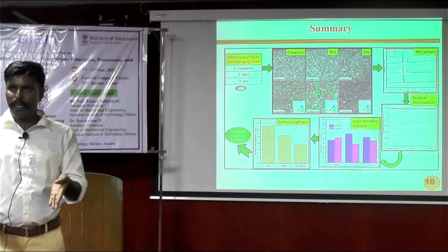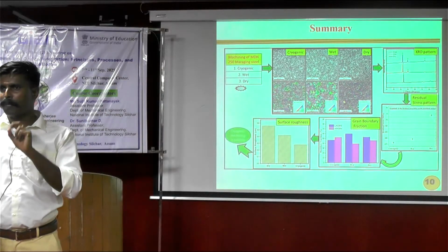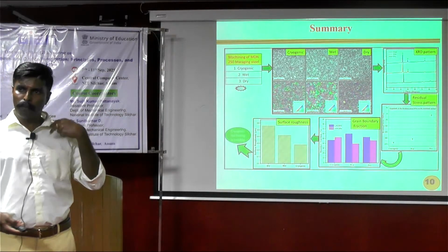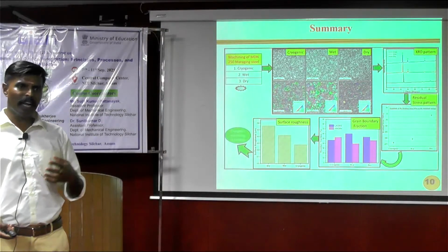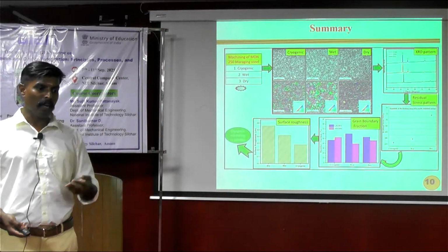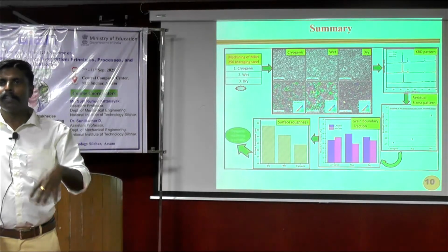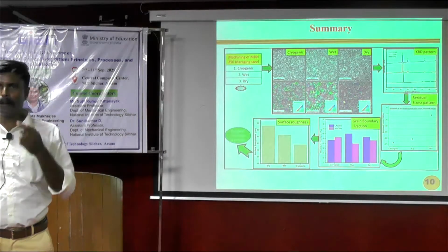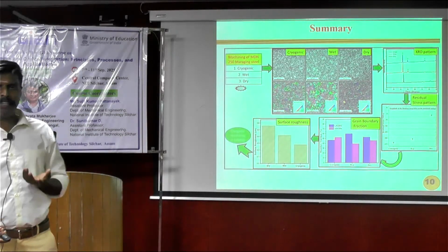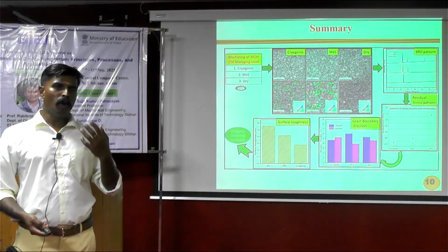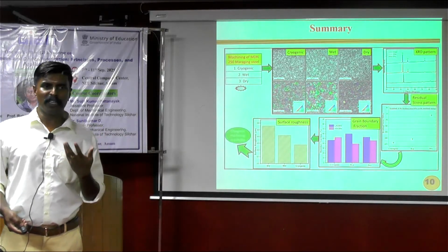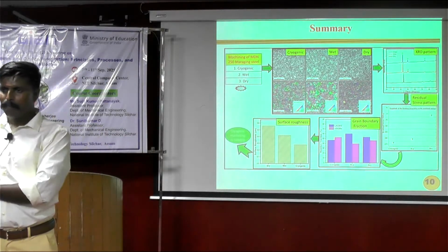If you do not know it, roughly as per a factor of safety of 2, you will start designing the material based on its yield strength. But whatever residual stress evolved in it will create the catastrophic mode of failure. So in order to avoid that, we are keen to know what the residual stress of the material will be by changing the machining environment.